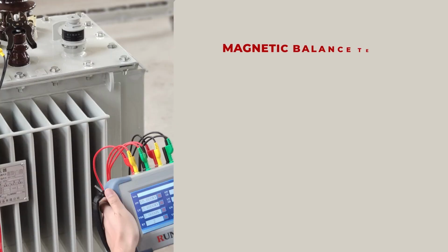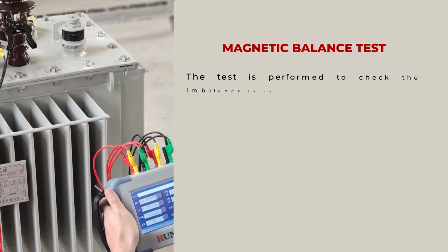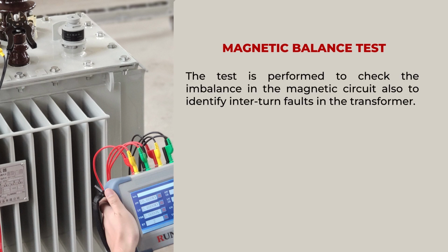Then the next electrical pre-commissioning check is the magnetic balance test. The test is performed to check the imbalance in the magnetic circuit and also to identify interturn faults in the transformer.